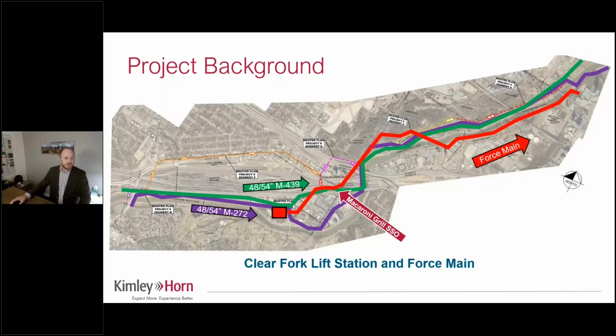So the solution here was to bring in a lift station, which is kind of a little weird to have in the middle of a system and not the bottom of a basin, and then effectively pump around these choke points in a pretty heavily developed area. Since with a pressure pipe, there's a little more flexibility for installation horizontally and vertically. And so the rest of the focus will be on the force main installation itself and then the directional drill.